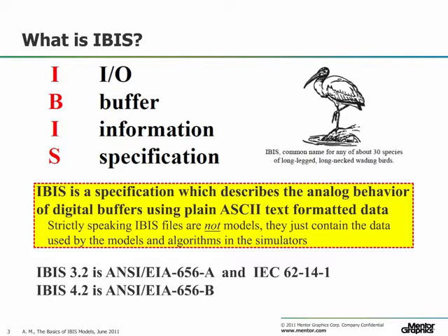So strictly speaking, IBIS files are not models, they are just data containers which contain the data for the models which are implemented in the tools, the simulators. Some versions of the IBIS specifications have been standardized, and you can see those numbers on the bottom of this slide. The standardization of the latest version of the IBIS specification is ongoing work in progress.